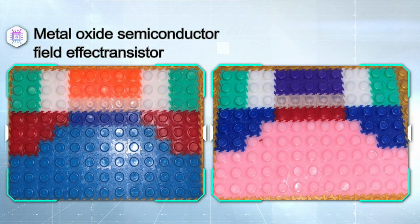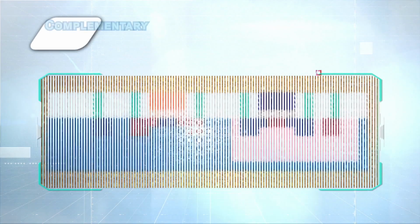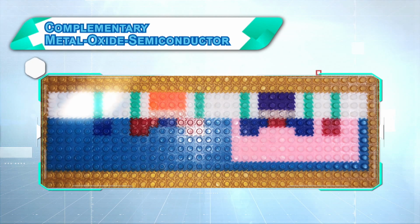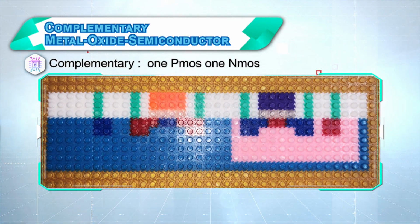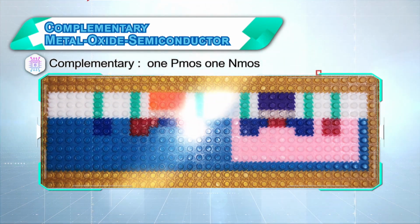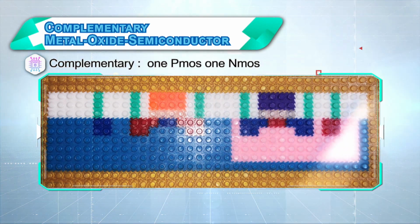Now MOSFET, there are two major types. One is the P type, one is the N type. P stands for positive. The current that flows through the channel is a positive charge. The current that flows through the N type is the electron itself, stands for negative, N stands for negative. In the application, we always put the N type and the P type together right next to each other. So one control gate can control the N type and the P type at the same time. In that case, we call it complementary metal oxide semiconductor, stands for CMOS.